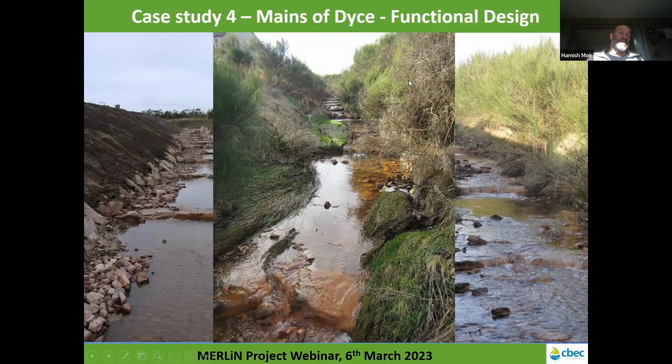None of the steps have moved, although because we incorporated natural channel form in the design, there actually has been some adjustment of the channel. So the channel's been able to adjust its form by moving these cobble benches around to a more natural equilibrium state. Because we've incorporated process in the design, it has been able to adjust and refine its morphology to be optimal for energy expenditure. This channel has now experienced much bigger flood events than caused the erosion in the first place, and is entirely stable. So, a really good example of how applying this nature-based approach and reproducing natural channel form works very effectively.